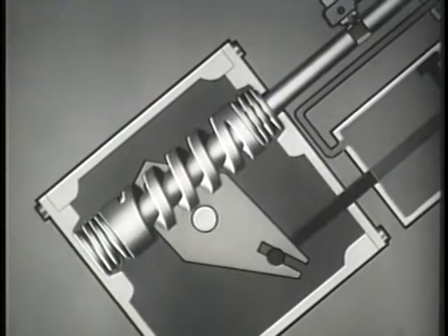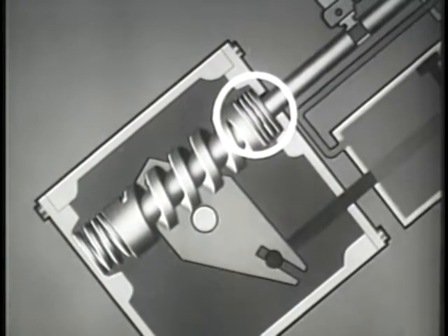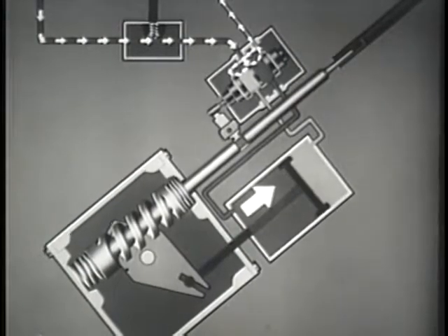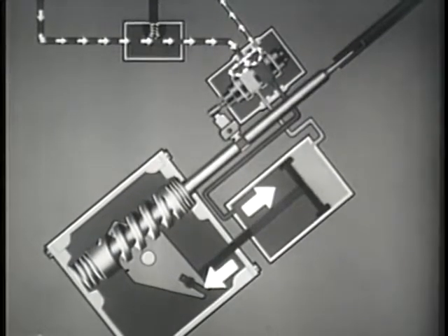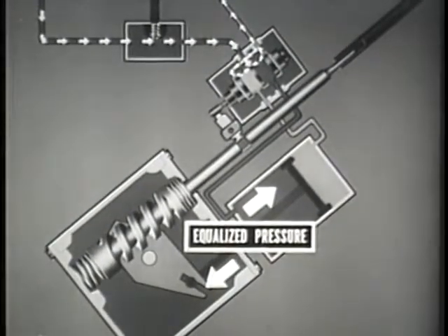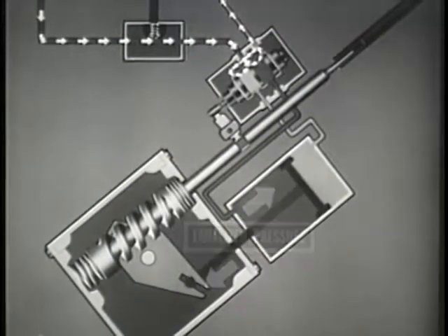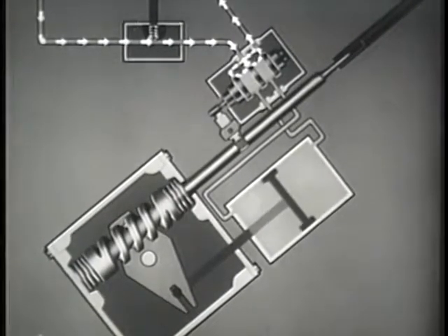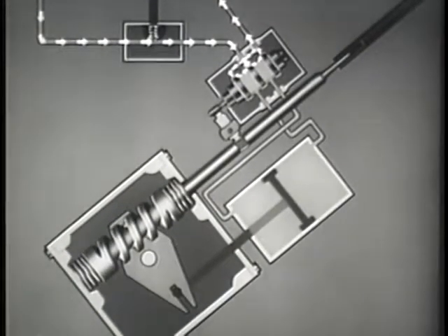These two opposing forces cause the steering cam to partially compress the upper cam spring. This also moves the control valve linkage and positions the valve spool where fluid pressure will equalize the force exerted by the steering geometry acting on the piston rod. The front wheels can then be held in any desired degree of turn. On return to neutral, all fluid from the pump is directed back to the reservoir. The pressure is lowered throughout the hydraulic system, and the piston and piston rod do not function.